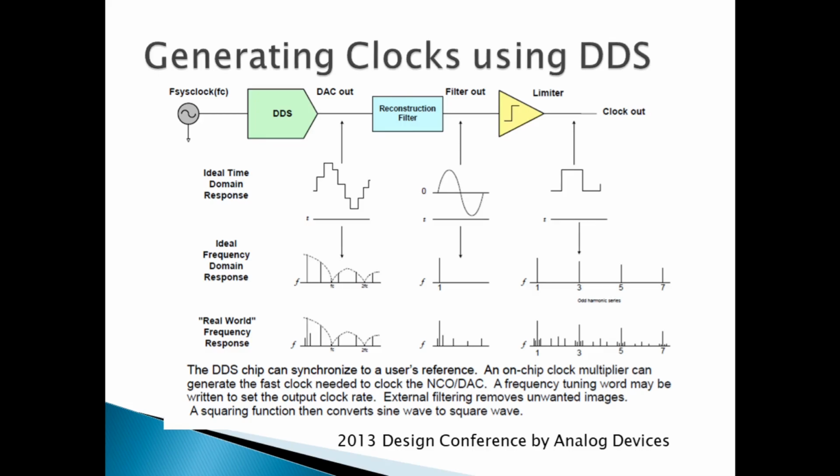The accumulator will pick up various points from the sine wave, that is from the lookup table, and will apply it to a D to A converter which converts it into analog domain. Obviously, over time, these points will make a sine wave.